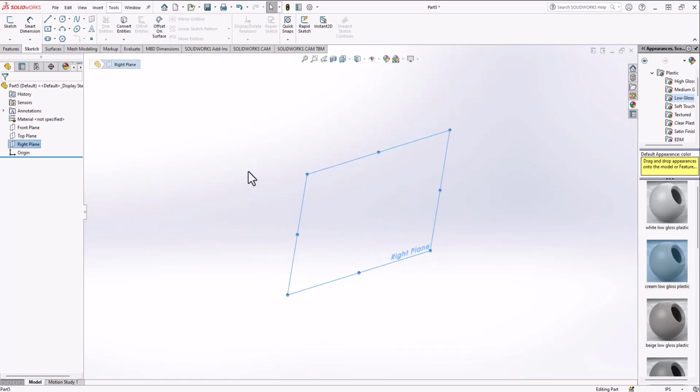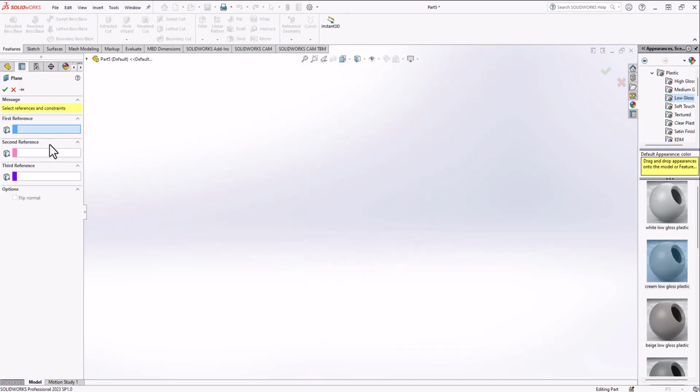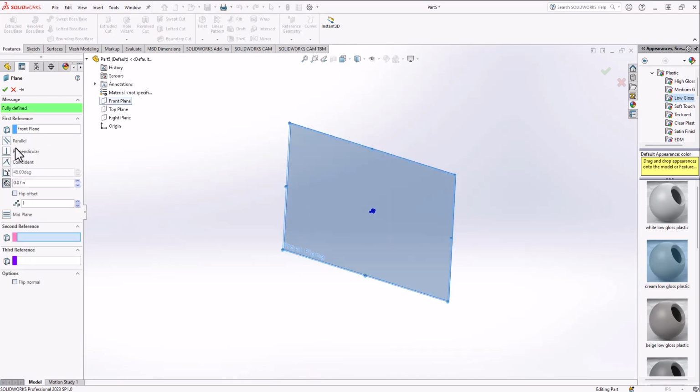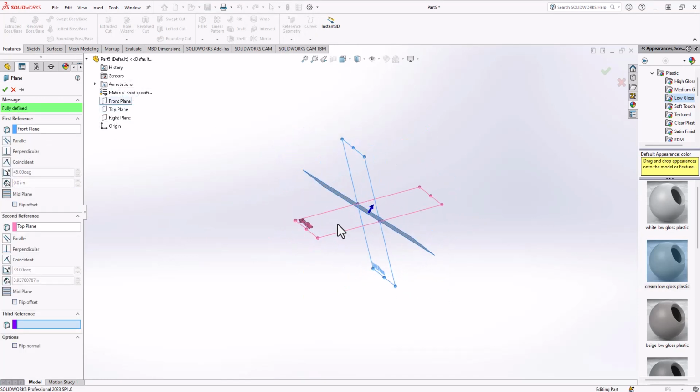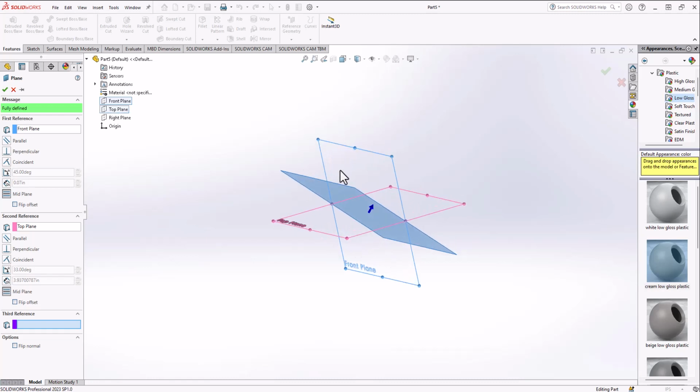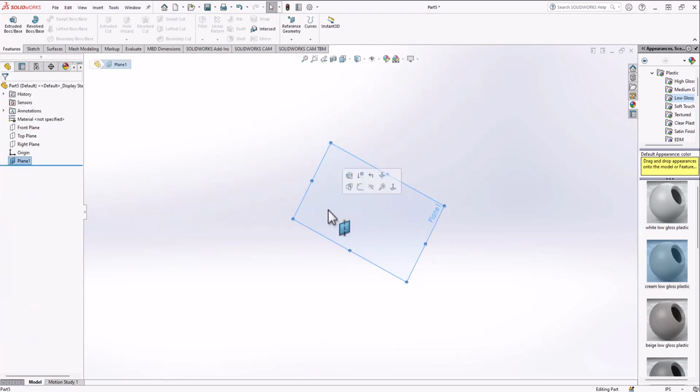So what you do for a sketch is you click on the plane you want to work with, so whichever of these, or if you want to work with a separate plane, you can go to reference plane. So I'm just going to do a plane that's kind of 45 degrees off of 2 existing planes, just to do something interesting. So you can create these extra planes. Generally you want to start with one of the primary 3, but I'm going to start with this one just to show working on a different plane.